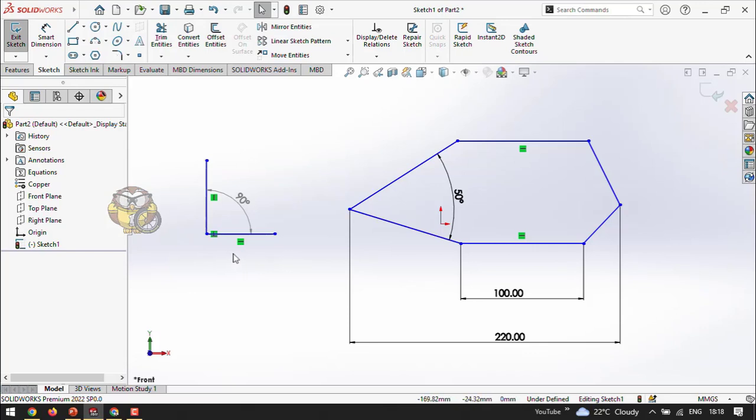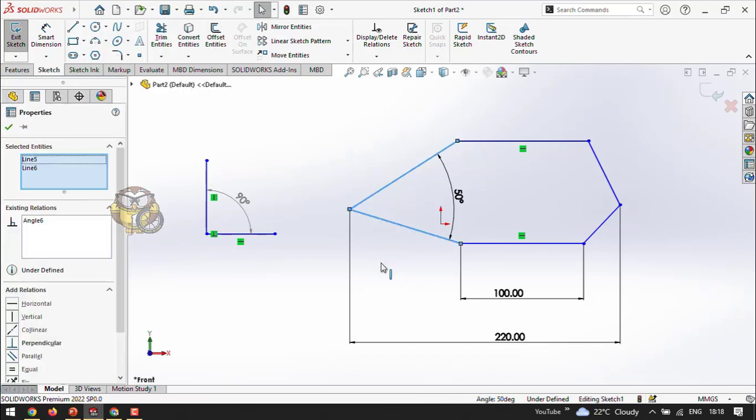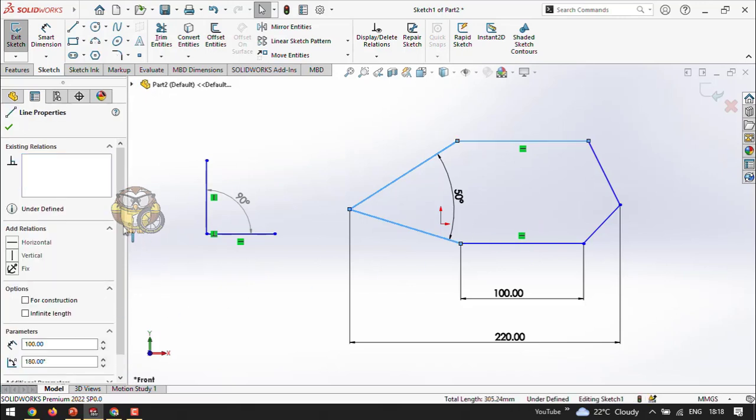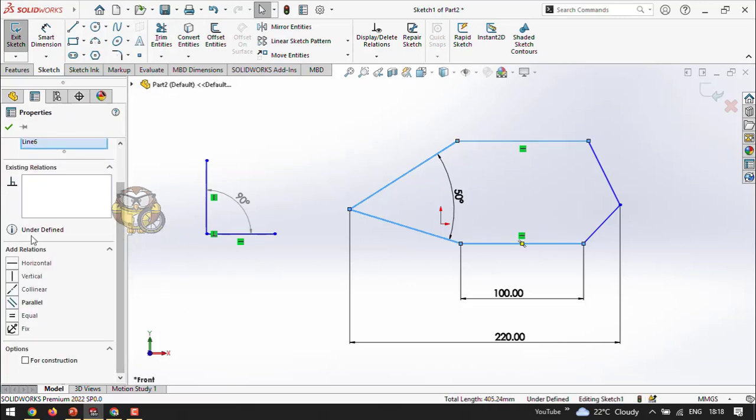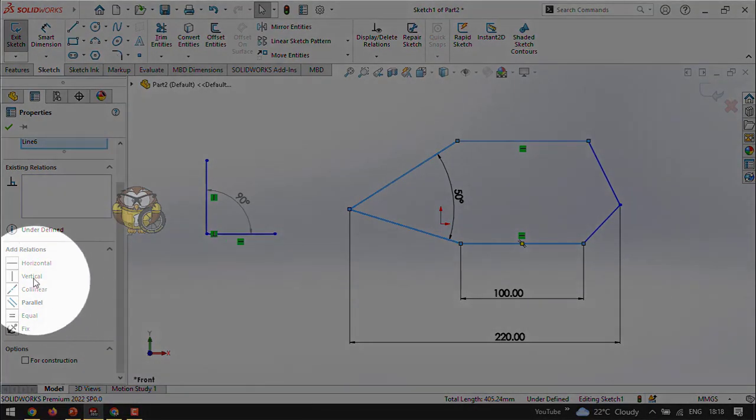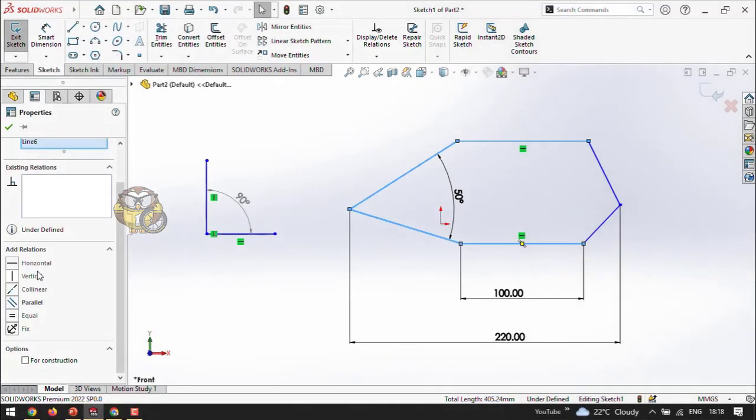So just now you understood how the constraint is working. Now I give the escape command to come out from the previous command. I select this line and this line, and I can also select all the lines. Whenever you select different lines, the constraints available change. Now some constraints we cannot see, especially for 90°, parallel or perpendicular, because we are selecting 3-4 lines.